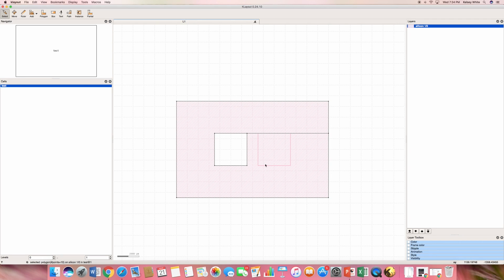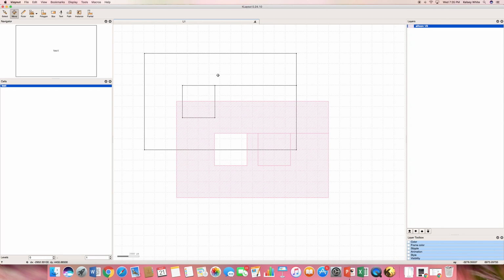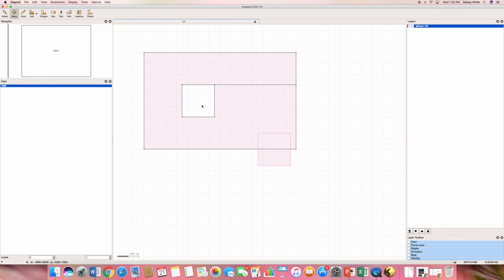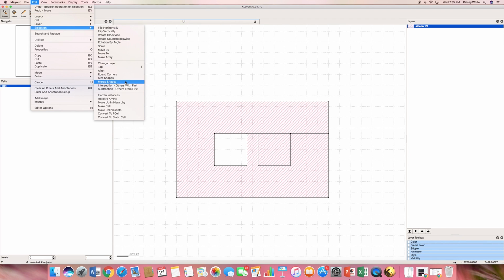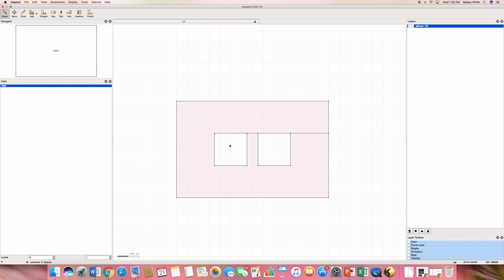I'm going to click this outer object, which is now combined. I can actually move it around with the cut inside of it. That's just fine. I'm going to Command Z, put it back in place. Now I select this outer object because I want to cut out of it this smaller circle, or smaller square, excuse me. I'm going to subtract it, and there I have it. So I have two holes cut out of this box, and maybe I want to make some channels between these